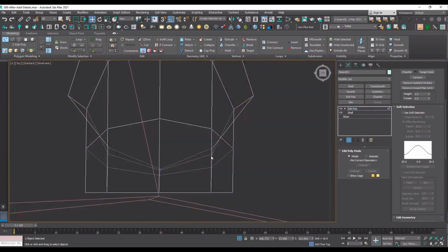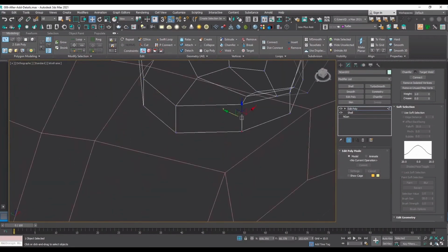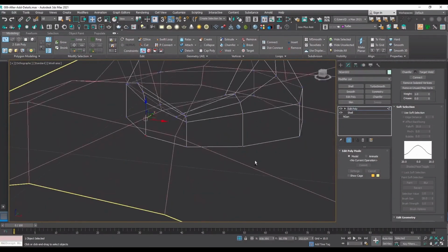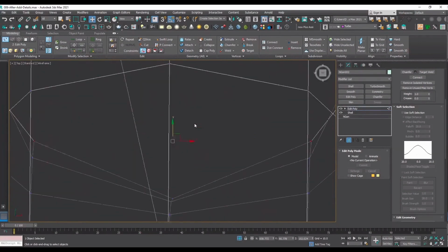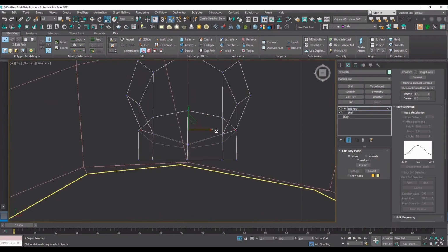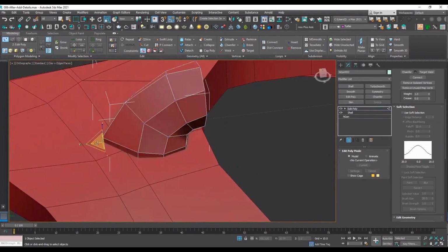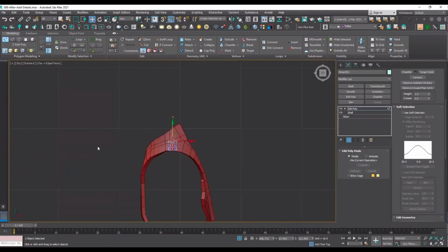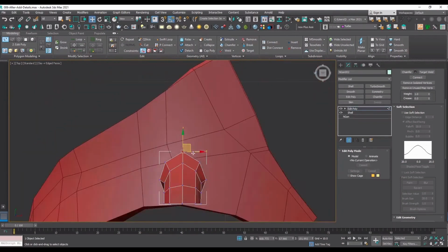So still now I'm adjusting the vertices so that I can attach this part that we are modeling to the surface underneath. So we have to put the proper distance between the vertices for them to get a nice shading and not be distorted or jagged.